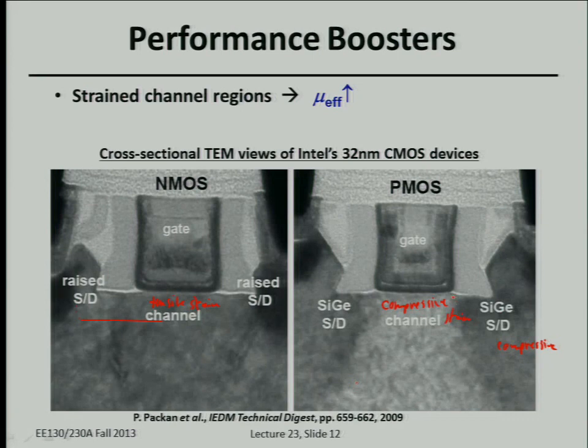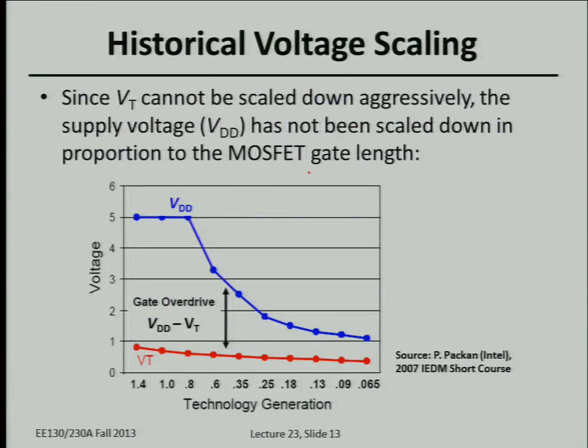No, they still have source drain extensions like here, doped source drain extension regions here, and this is the spacer, the gate sidewall dielectric spacer. But then they raise the source and drain regions, and here's the tungsten, the metal plugs that contact the source and drain regions. Okay? Yeah, good observation.